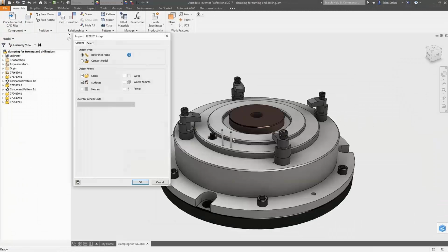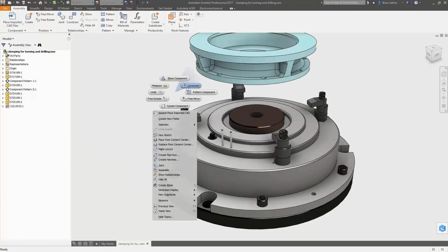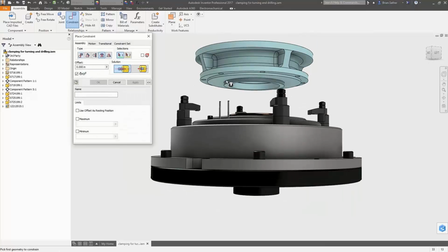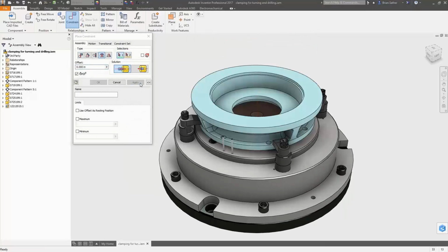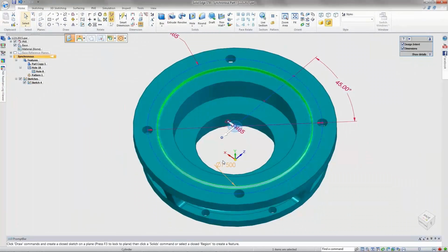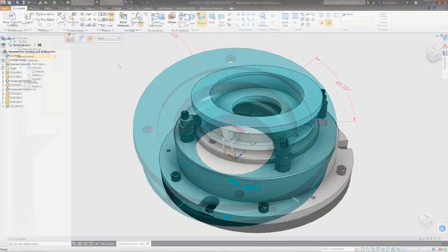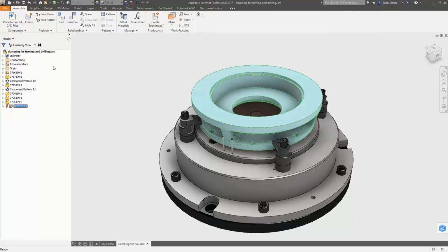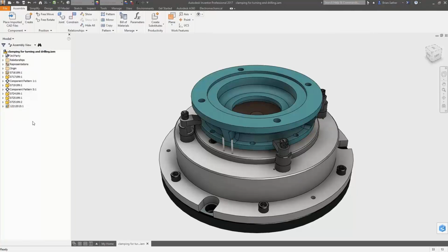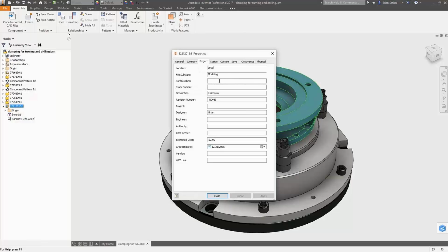So inside of Inventor, we can use or reference a STEP file and bring it into our design environment, remembering we're not converting the file, so we're not creating an additional file to reference and have to manage. In this case, we can then go and add constraints to the geometry. But the great thing is, if we go back in the original geometry creation environment, in this case Solid Edge, and make a change to it, if that file is then exported as the STEP file, you'll note that the design shows that the feature is out of date. We simply update it and the changes flow through into the environment. So all of our constraints are maintained.